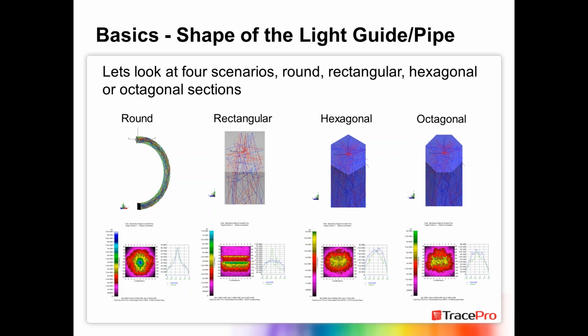Okay, and another question here. Where in the software is the lit appearance function? There are two places. Thanks for asking that. We have a photorealistic rendering. It's underneath our view menu. And what you do is you set the view up in the system view the way that you want. Then you specify if you want to have an ambient source, or if you want to use the internal sources that you defined in TracePro. And then you specify the exact view in terms of if you want a forward view or a side view. You specify that in the system view using the view set view command.